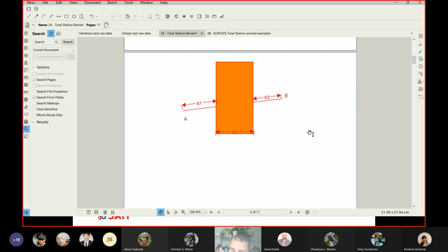Okay, I'm going to give you the answer. Everything on the screen is completely wrong, and I'll tell you why it's wrong and why it's impractical. It's wrong because the three distances x1, x2, x3 are not along the line. They are zigzag. You measure x1 in between A and B, and then x2 has a different direction and x3 has a different direction, which means adding them together, even if you're able to measure them, is not correct.